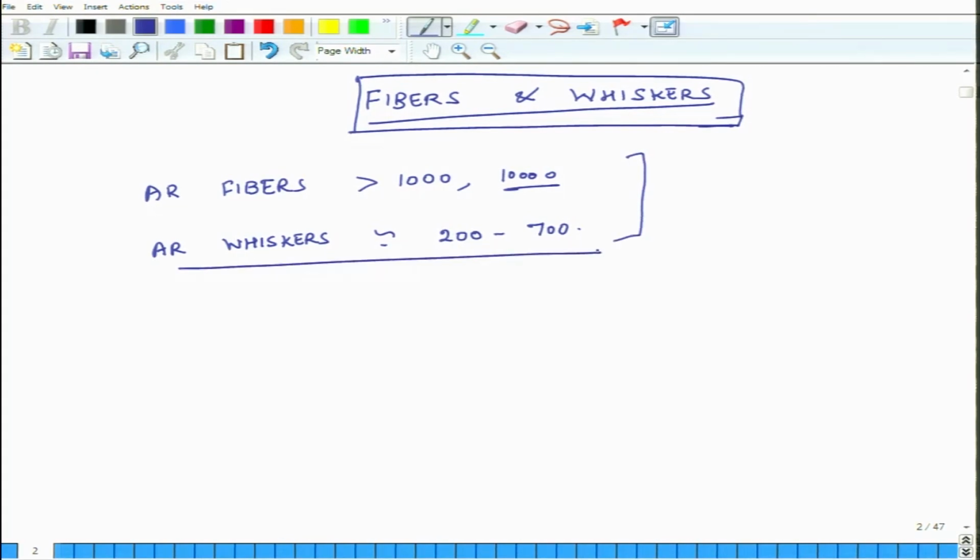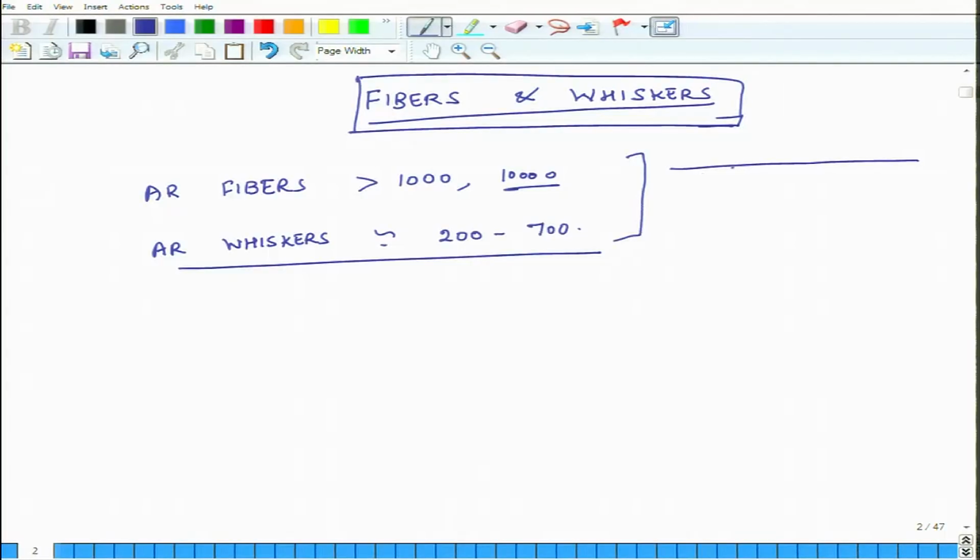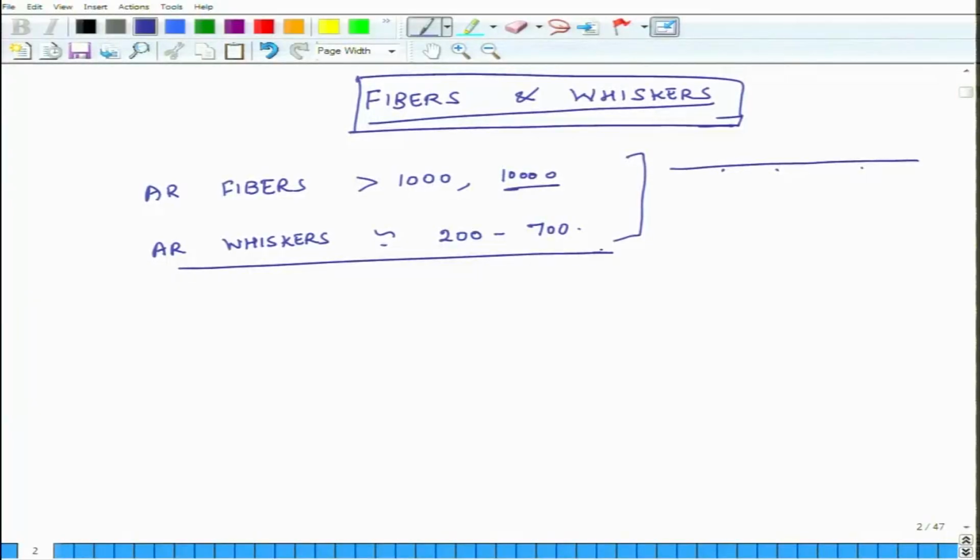This is one difference in geometry. For the reasons which we had discussed earlier, because these fibers are long and very thin, the chances of having a flaw in the fiber is very less. They are almost flawless structures, there are not many flaws along the length, but still fibers have some flaws. But whiskers are super pure and almost flawless, though they are smaller in length. As a consequence, because of their extreme purity and flawlessness, the material properties of whiskers are even higher than that of fibers.